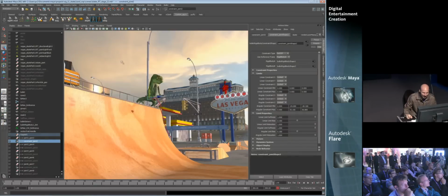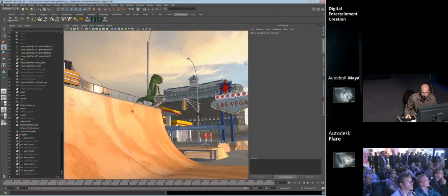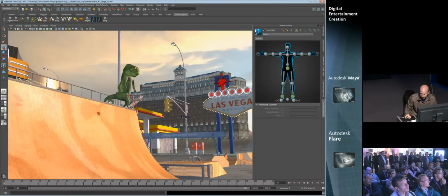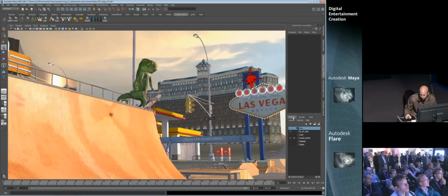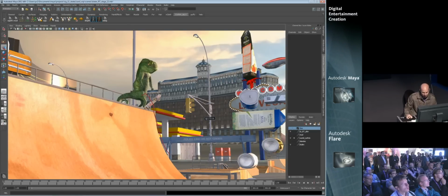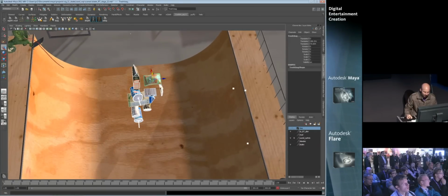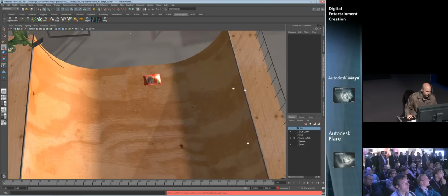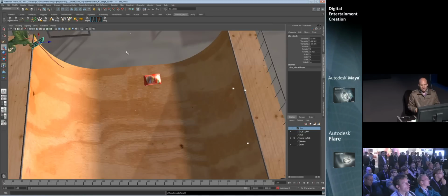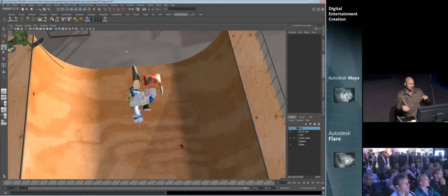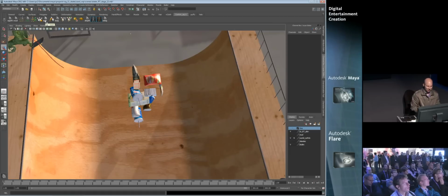The next thing that we want to do is just add in a few more objects. Let's just pop that guy and get back to my control box here. Display layers, we'll put bullet on. So I've got these other objects in my scene. I want to have them be rigid bodies, so we'll select them all, accept that bag. We'll create the rigid body for this guy, so it'll go through and think about that. Actually, I'm going to create an OGS reset there. So I'm running a beta version of this, I should mention that. When I created the rigid body, the OGS draw lost what it was. The command is OGS-reset. So if anybody's using mine and something weird happens in your view, OGS-reset will reset it for you.